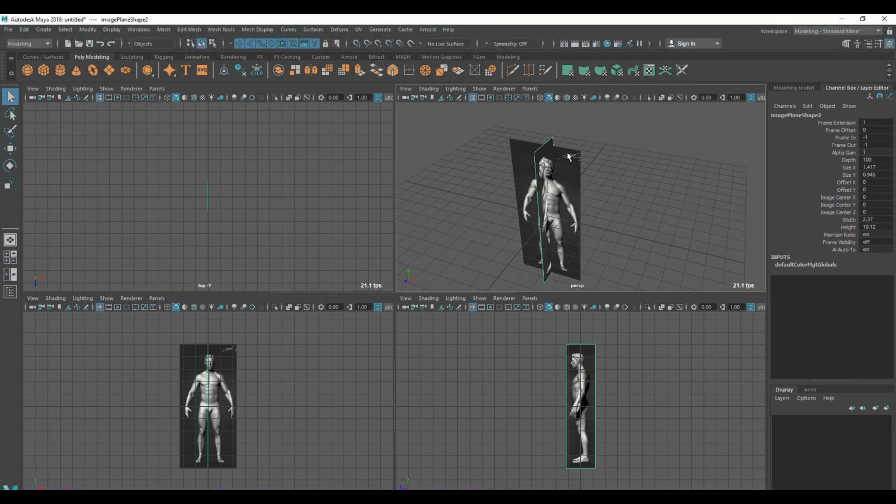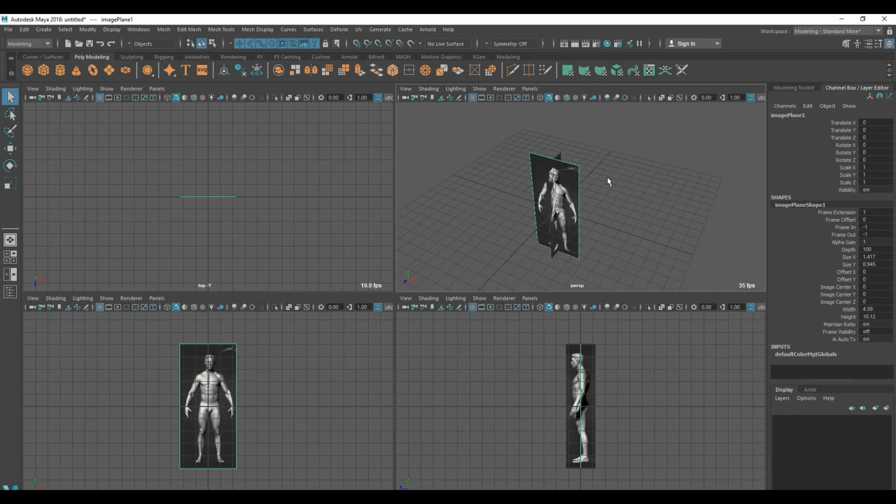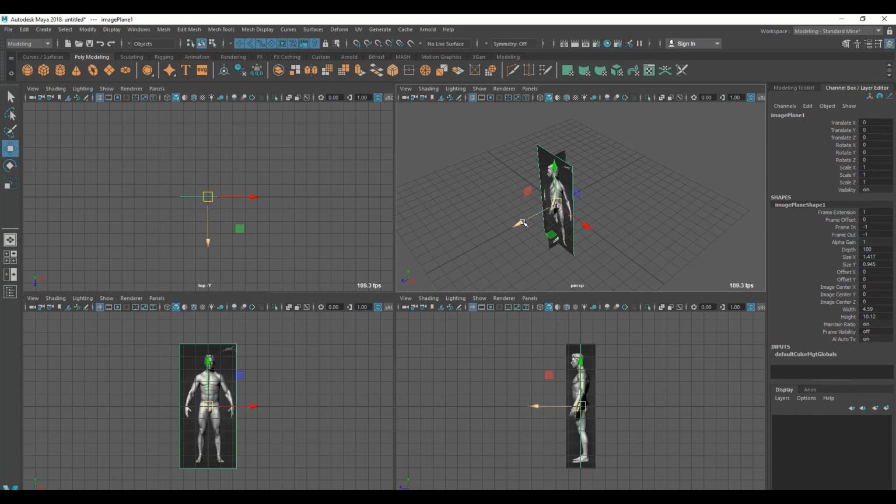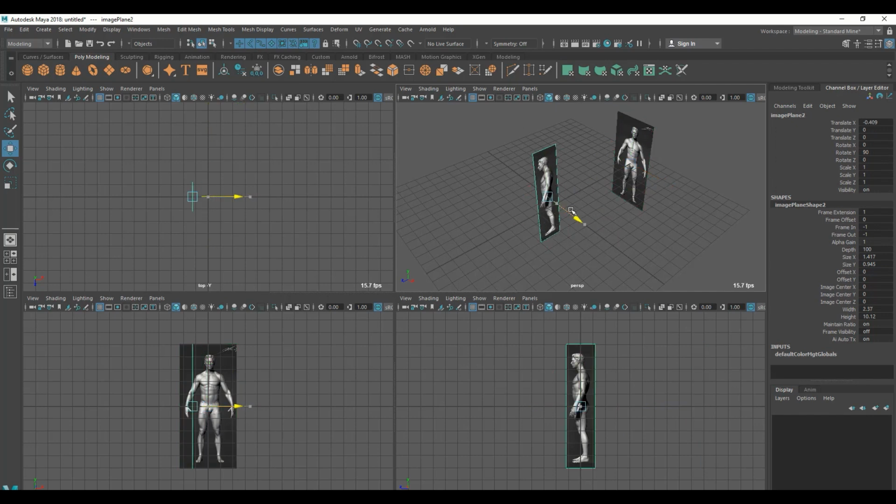Now I'm going to just move them. Just click here with the select tool, click on this front view, take the move tool and move it in the -Z axis, meaning the opposite Z. You can see this arrow direction, this side, just go opposite. And again select it and go X opposite.